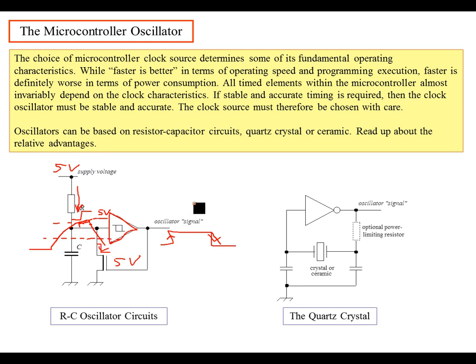So basically, you're going to have this Schmitt trigger level like this, where the capacitor is going to charge at an RC time constant like this. That's the initial charge, and then it's going to fall until you hit this level. Then it's going to charge again at an RC time constant, and then it's going to be discharged again by the MOSFET. So this period of time here is the MOSFET discharge cycle.